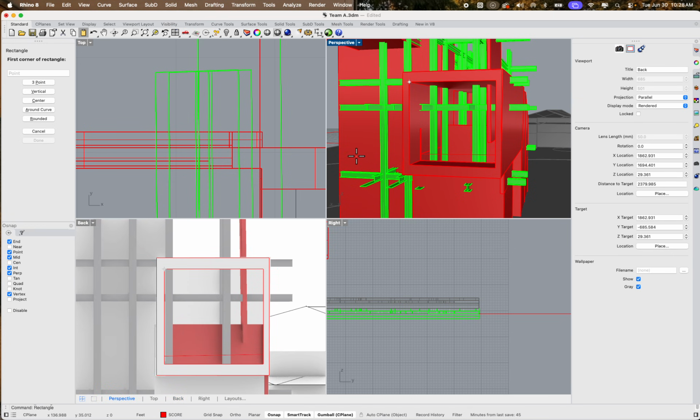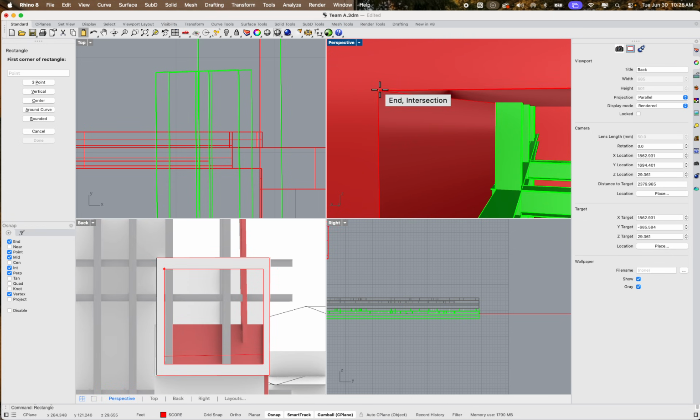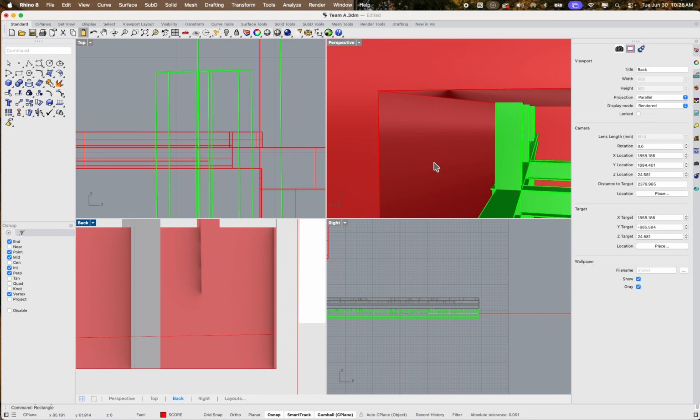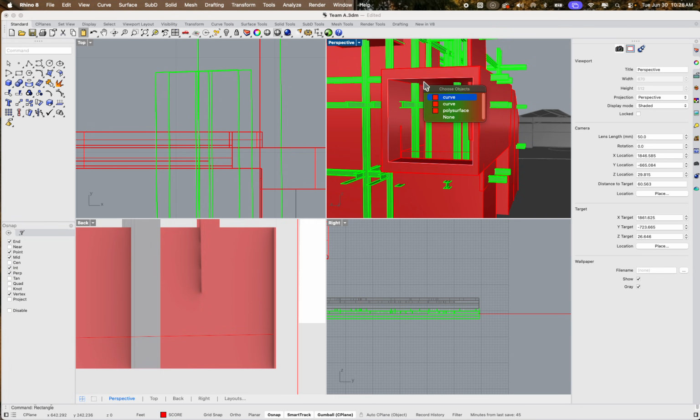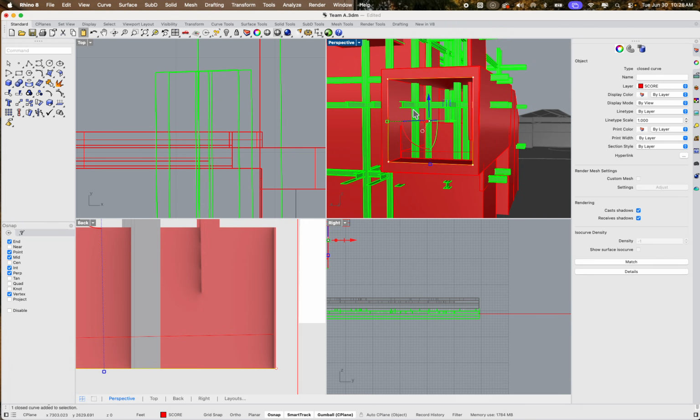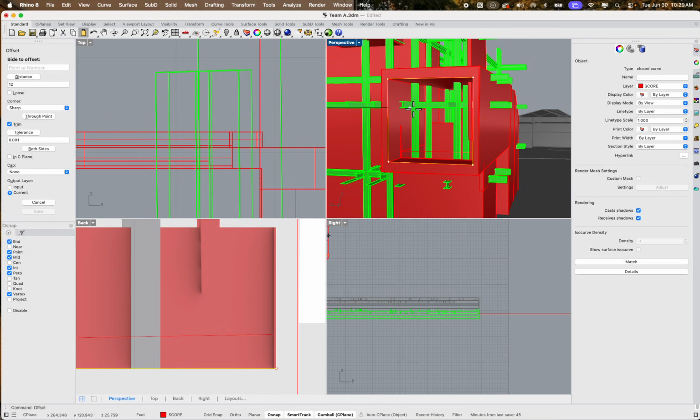So we'll take that piece, and sometimes you can actually use a little bit of both. There we go. Fantastic. Alright, now we're getting somewhere. Offset, typical mullion size. You can actually even measure these ones, but it's about 2 inches. Kind of like the 2x4, it's really usually 1.5 by 6. So in my case, I'm going to offset that, kind of an inner thickness. So we'll go 2 inches for today.